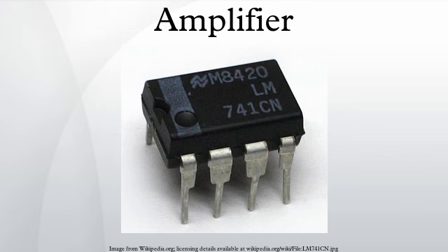Another advantage of the Class D amplifier is that it can operate from a digital signal source without requiring a digital to analog converter to convert the signal to analog form first. If the signal source is in digital form, such as in a digital media player or computer sound card, the digital circuitry can convert the binary digital signal directly to a pulse width modulation signal to be applied to the amplifier, simplifying the circuitry considerably.